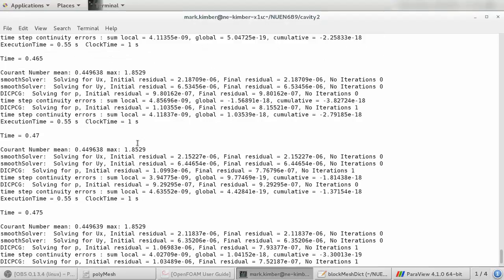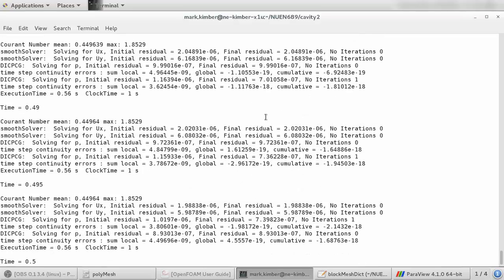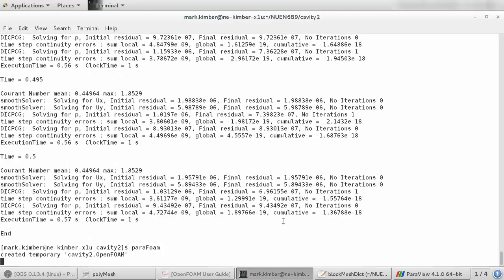Since the delta t is the same and my mesh is uniform, that means my delta x is the same. So the Courant number is maximum where the velocity is the highest, right near that wall. But we still are iterating and finding small residuals below our cutoff criteria, and so the solution is not blowing up.